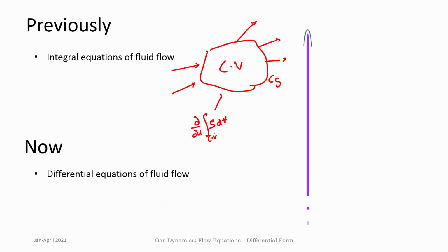of the control volume. If there are any changes to that mass, it should have happened due to fluxes around the control surface, which is rho v dot n dA, where n is a normal. So, this is really the flux of mass, and since the total mass never changes, this is equal to 0. So, this is the conservation of mass.